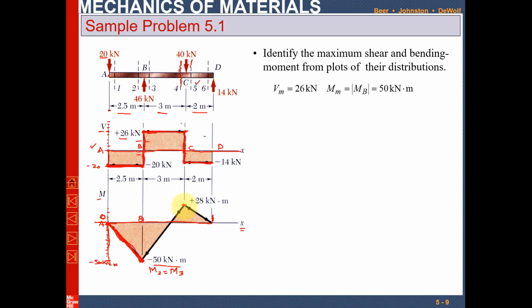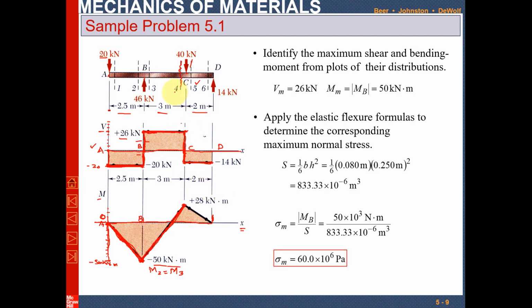Again, you have to join this point with this point. You will see the shear force line. This shear force is a 0 degree line, and again the bending moment line will be linear. So you can easily join point B with point C with a straight line. Now at point C, we check the moment at points 4 and 5.